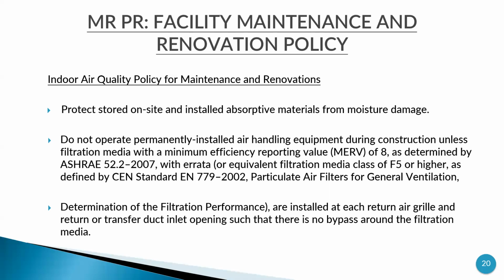Wherever the filter media is used, generally everywhere. Determination of the filtration performance: filters are installed at each return air grille and return or transfer duct inlet opening such that there is no bypass around the filtration media.